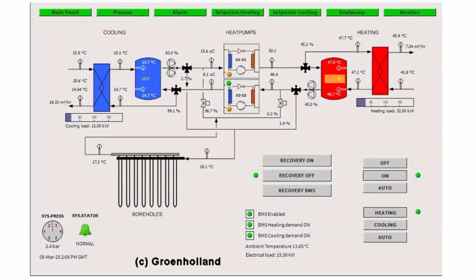The heat pumps in this case can provide cooling to the building on the evaporator side and heating to the building on the condenser side. The heat delivered to the building is regulated by a 3-port valve to the plate heat exchanger, where any warm water generated by the heat pump that is not being used is put into the buffer tank. The return from the plate heat exchanger also goes into the buffer tank,